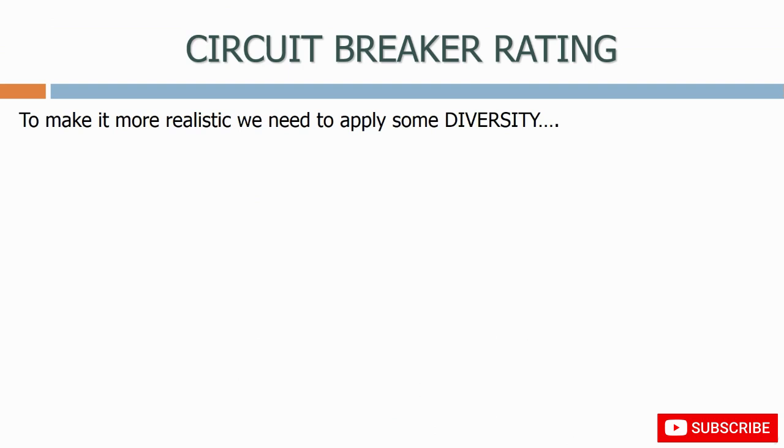To make it more realistic, we need to apply some diversity. Diversity is a way of applying common sense and using our knowledge of the system to give us a more realistic figure of what the load drawn from the system might be.